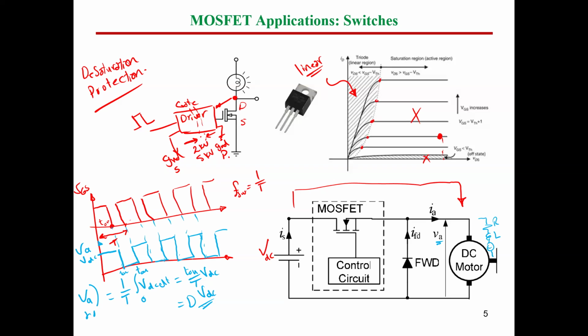So, in order to protect against losing the current in any inductive load, we use such a diode. It's called freewheeling diode. So what will happen? Once you disconnect the switch, the MOSFET switch here, this is going to be open circuit.